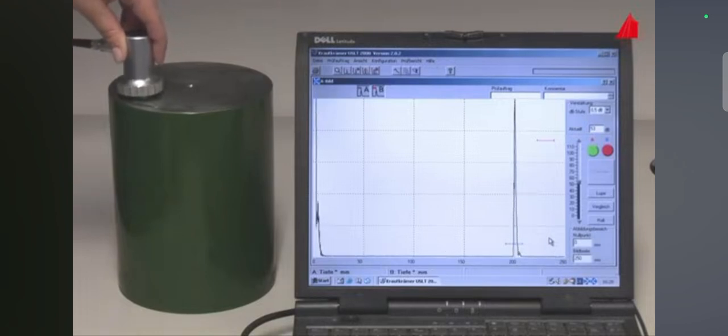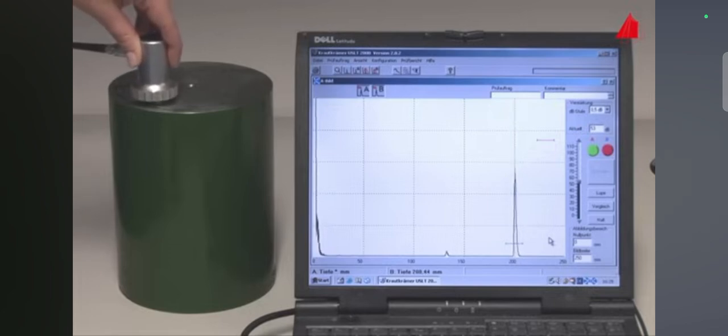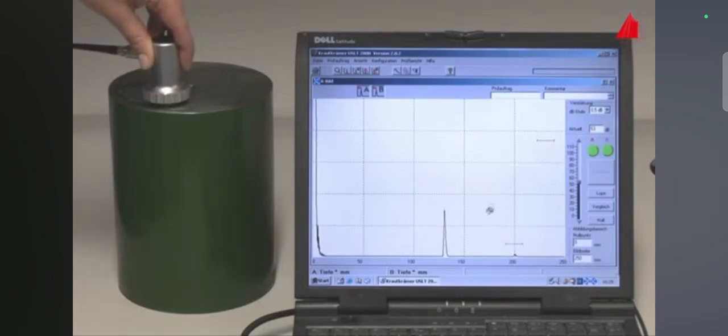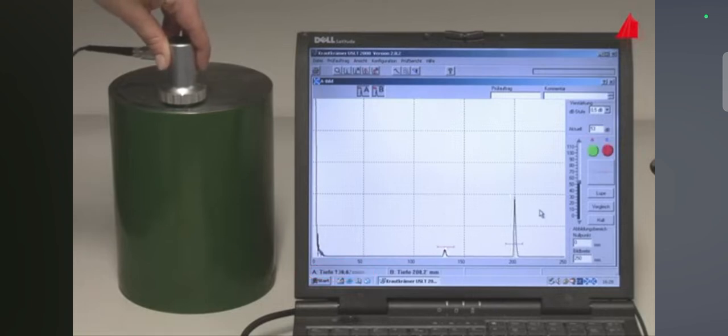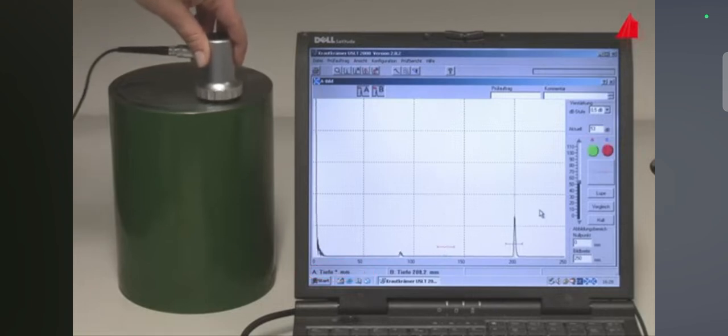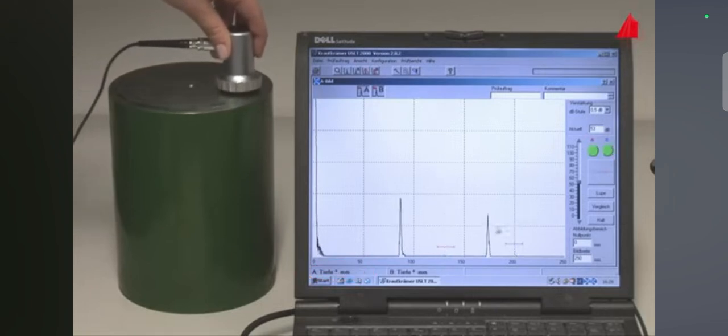The material tester scans the upper front end of the cylinder with the probe and observes the monitor. A defect echo appears on the monitor. This defect is located in a depth of 130 millimeters below the surface. Another echo indicates a defect in a depth of 87 millimeters. The second smaller echo at 174 millimeters is caused by double reflection on the same imperfection.